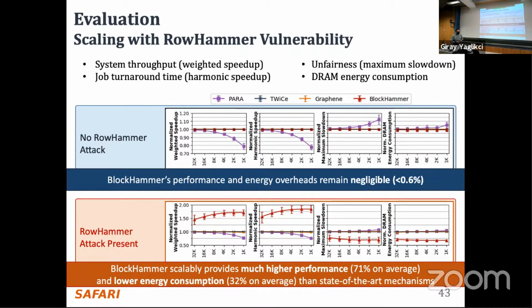And so here, what we use is basically the state-of-the-art configuration used for improving row buffer locality. So it's not like just sequentially writing the data into different rows from beginning to end, for example. So you put a bunch of data in some place in a row, and then you move to another bank, and then put some other data over there.